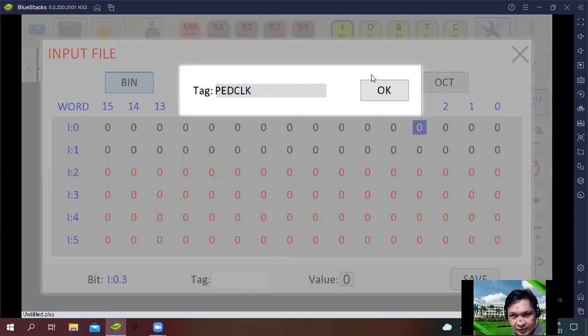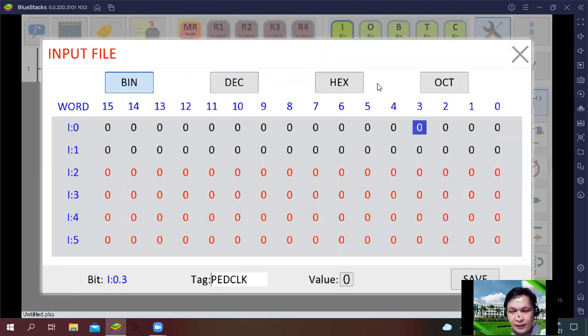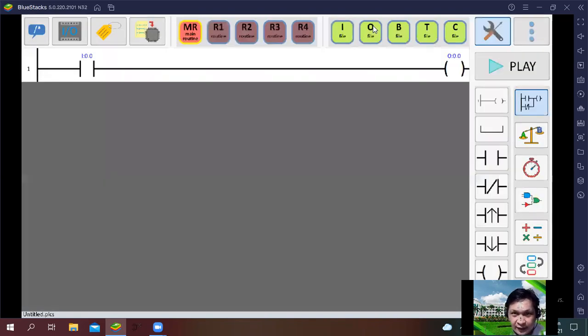Again, if you're just checking out the number of pulses or the movement, it doesn't matter too much if you use the clock or the data. But if you want to learn the direction of the shift, you need both the clock and the data present in your program. Okay, so that does it for the input.